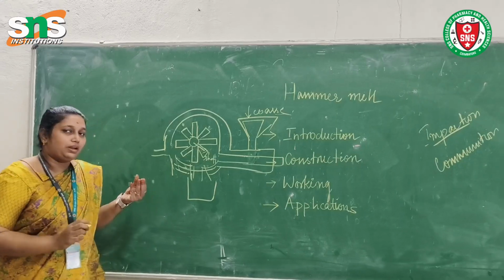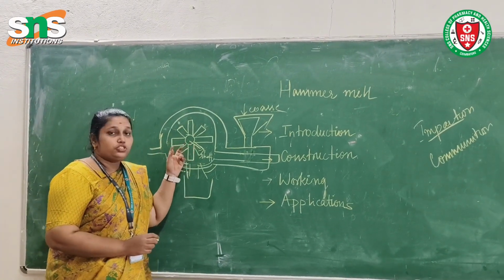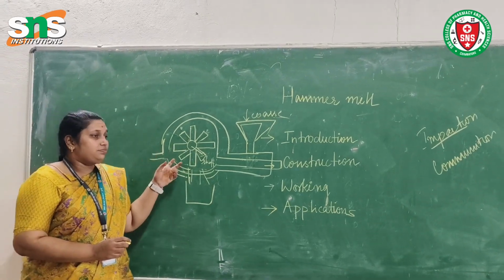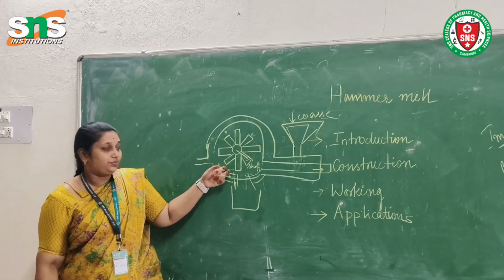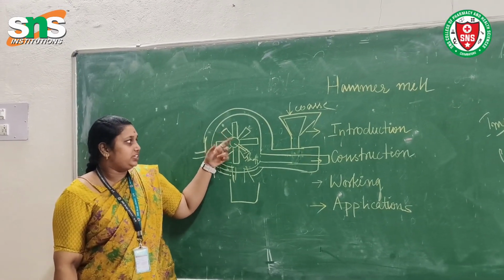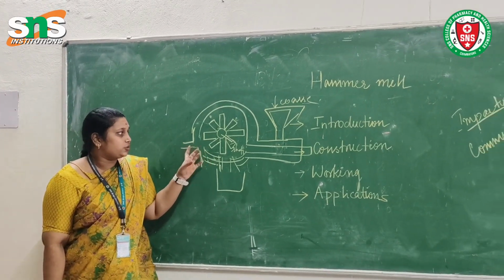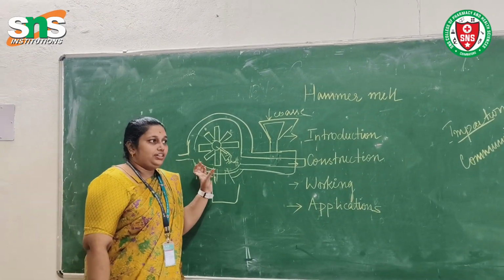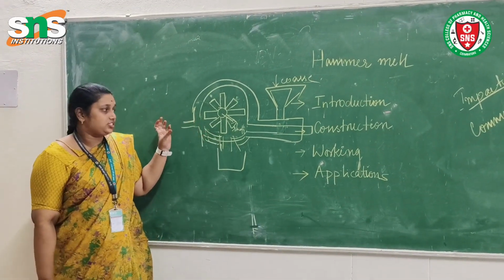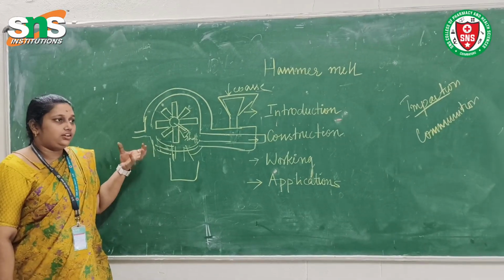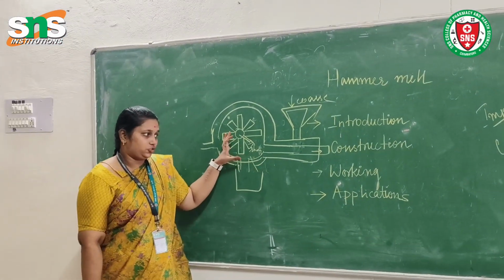The screen is made up of plastic substances which is closed for a circular motion while the size reduced particles are in random motion. Now there is a disadvantage: these hammers are in a rotating motion continuously, so they get heated, which may affect thermolabile substances, and we cannot put hard objects such as stones or stone-like materials or very hard materials into this.